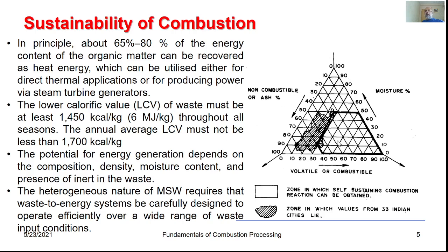As you consider the typical Indian situation, in order to have the combustion be a self-sustaining operation, the moisture should be less than 50%, the volatile content should be more than 40%, and the inert content should be less than 50%.